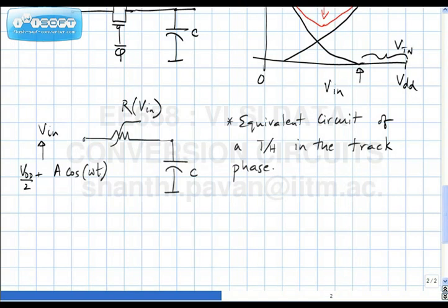You will see harmonics, and an index of how good, or how close to linear, the so-called sample and hold is, is the amplitude of the harmonics relative to the fundamental. That sounds like a reasonable definition.